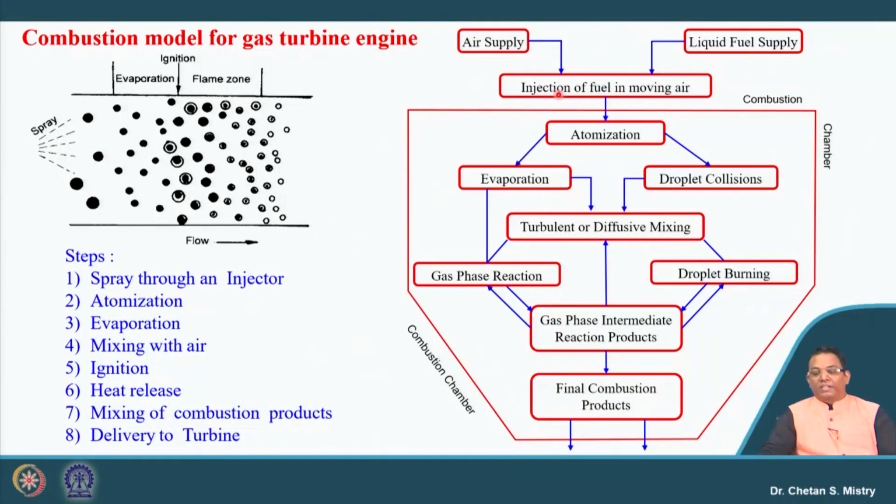In this case, the fuel will be injected and subjected to atomization. When we say atomization, it involves evaporation and droplet formation. These two together increase the turbulent intensity inside and give proper mixing, which then gives the gaseous phase reaction and droplet burning.